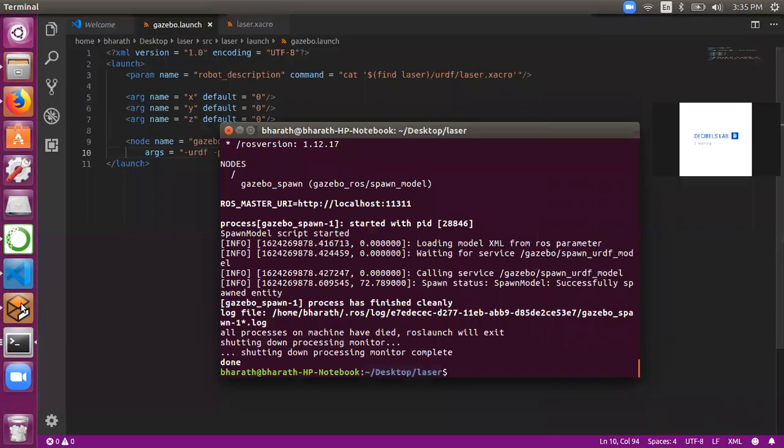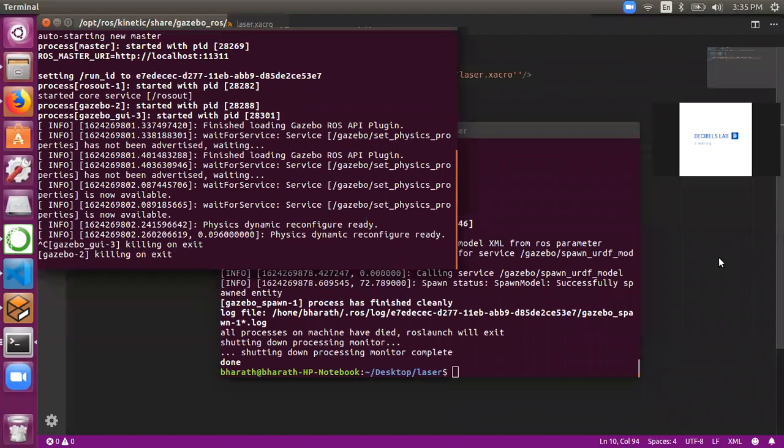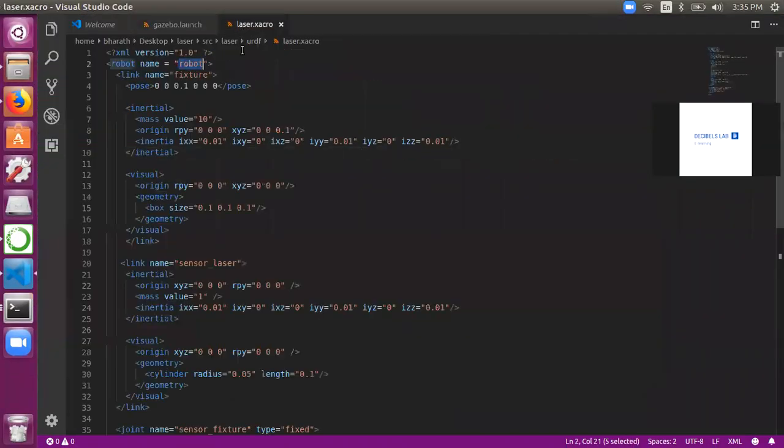So these parameters we have not defined, so that's why we're not able to see the robot. To define this out, I'll just stop this Gazebo, and over here let's type in the collision parameters. Collision parameters define, for example, that if two bodies are touching each other, we need to define certain parameters so that we could represent the collision between two links.